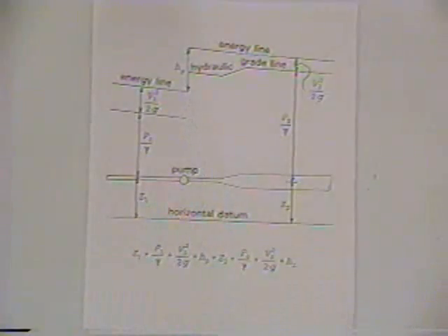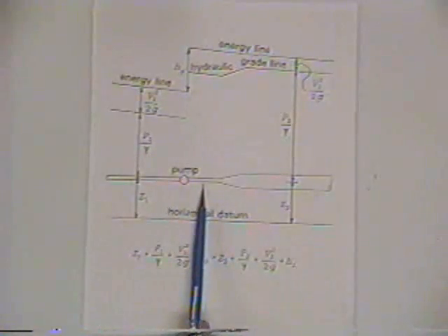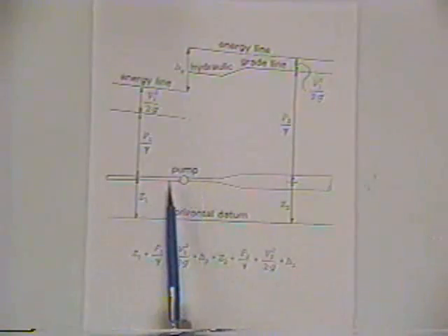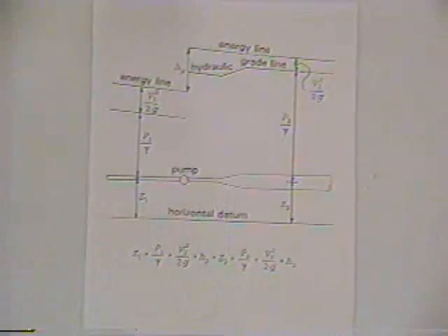It does nothing to the velocity. You know, intuitively, solving a problem, you might erroneously think in terms of the pump adding velocity, but it can't add velocity. The discharge is the same. Conservation of mass: flow in is equal to flow out. The only way you're going to change the velocity is to change the diameter of the pressure conduit.